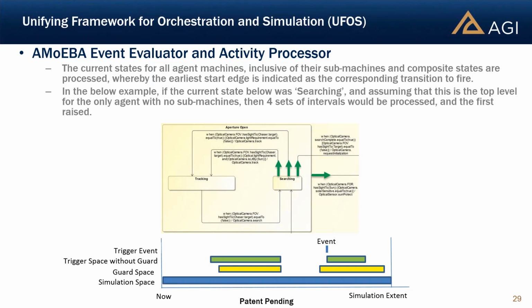So it does not require code to be written against the transition, other than the ontology statements that you see on the transition. I gave a demonstration at a No Magic Symposium once where I changed a statement on a state machine and hit go again. I had some hysteresis for a sensor that allowed it to go from tracking to searching with some other delays. I didn't have to write anything in the STK object model. I simply used the ontology to change the statements on the transition and hit go. That's how the integration is done, and that's the value of that type of integration: the integration is against the ontology.